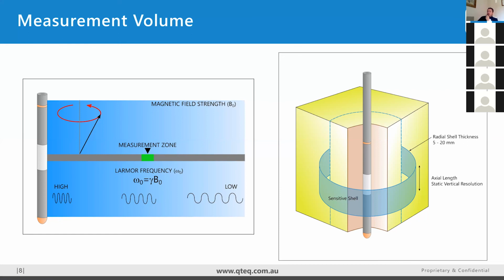So magnetic susceptibilities less than 500. I always get the units confused on this. I would have to confirm whether it's CGS or SI units. So anything less than 500, there's no effect. 500 to 1,000, you need to start paying a bit closer attention to the detail and the data. I imagine that's 10 to the minus 6 SI. Yes. Probably 10 to the minus 6 SI.